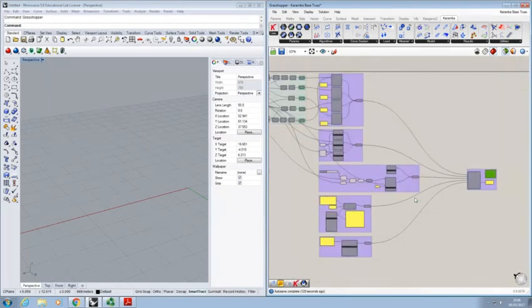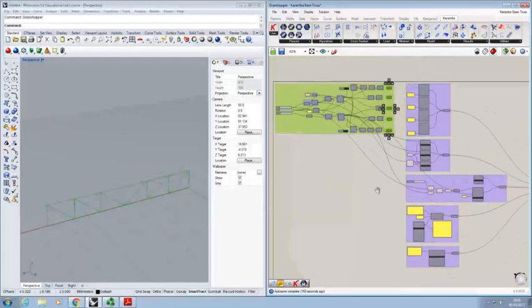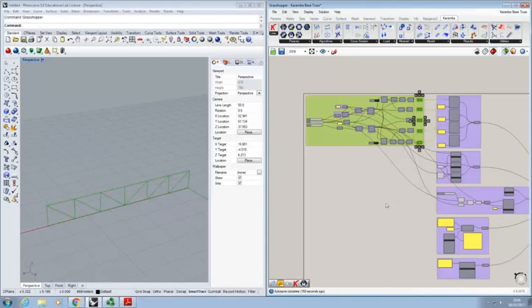The interesting thing here is that we've been building quite a bit without actually seeing what's going on. So I'm afraid that's the way Karamba is. You've got to have your geometry set up knowing that it's all kind of connected and it's fine. In any case, you run it, and if it doesn't work, you need to chase it back. But having it tidy, like I have it here, in a way that you can follow through and know in a very simple linear way what follows after what, helps you debug stuff later on.